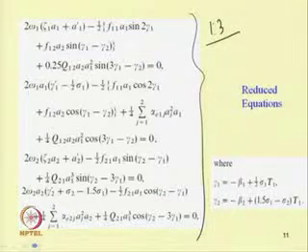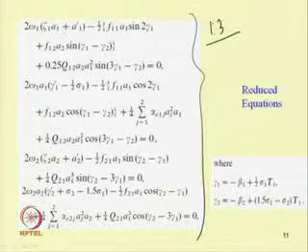Here a 1 gamma 1 are for the first mode and a 2 gamma 2 are for the second mode, considering 2 mode interaction. The non-dimensional first mode frequency is taken to be 1, and the second mode frequency is nearly 3 times the first mode, so the 1:3 internal resonance condition is considered.